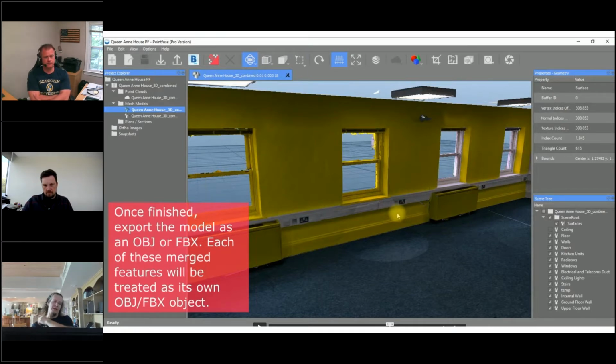And they're really great as an interim step for certain use cases, right? Or they may actually be a great deliverable. The tank analysis is the one that always comes to mind for me. People that want to get a tank, a big petroleum tank or a chemical tank, and they want to see if that's deforming as it gets filled, or if there's any fatigue issues. Having meshes that you can compare to each other is just a much lighter format than having 10 billion points over and over and over again of the same thing. But yeah, and that meshing process is highly automated.